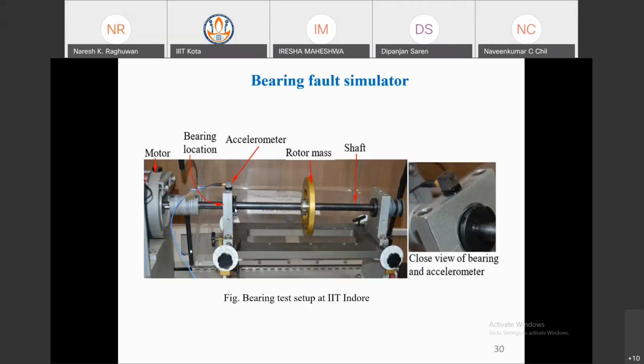the faulty bearing, with a fault in the outer race. The next time, generate the fault in the inner race, and the next time generate the fault in the balls of the ball bearing. Different faults you can insert for laboratory purposes, and you can see what type of variations appear in the signal for different faults as compared to the healthy bearing. Okay. Now